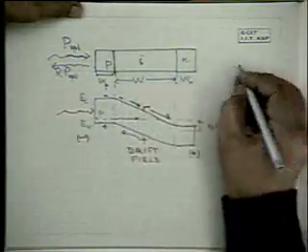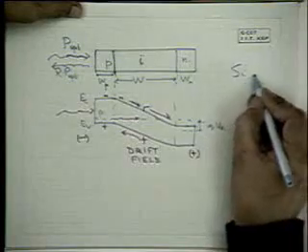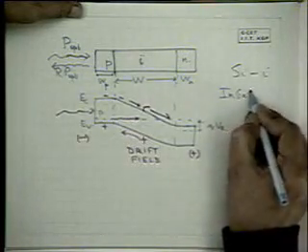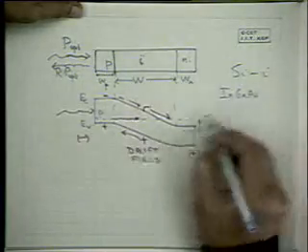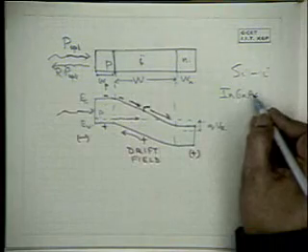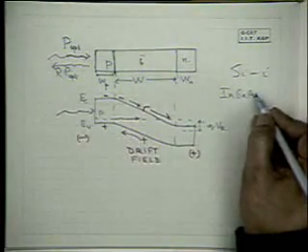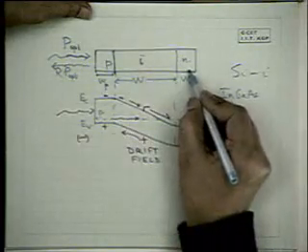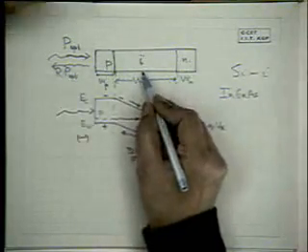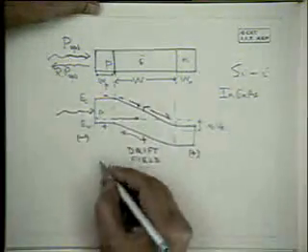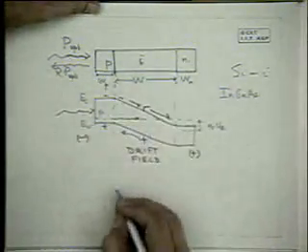But suppose you take InGaAs, indium gallium arsenide, which is used in infrared. It is difficult to get an exactly intrinsic material, but it can be high resistivity. If the carrier concentrations here are 10 to the power 17, 18, here the carrier concentrations will be 10 to the power 14. Okay, this is the electric field profile.